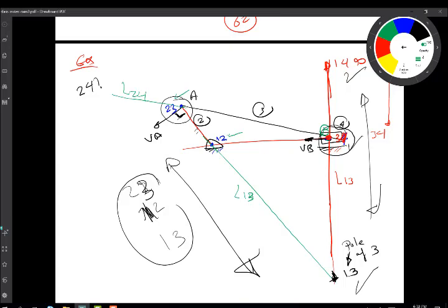Okay, now what if we have 1, 4 at infinity and 1, 2 here, which is a pivot of link number 2, so the common number is 1, the missing point was 2, 4. So I need to connect this point to this point at infinity, and this will give me a locus for 2, 4, correct?